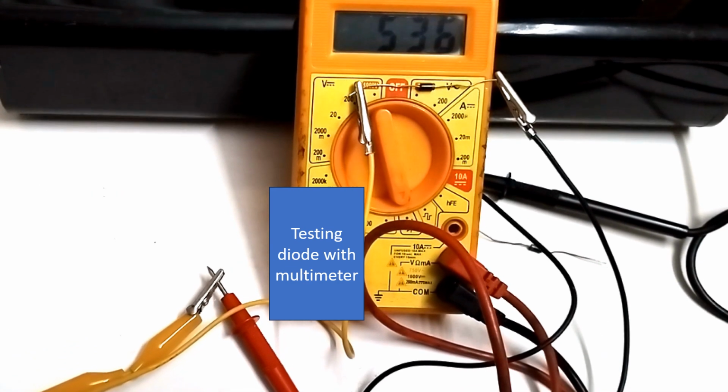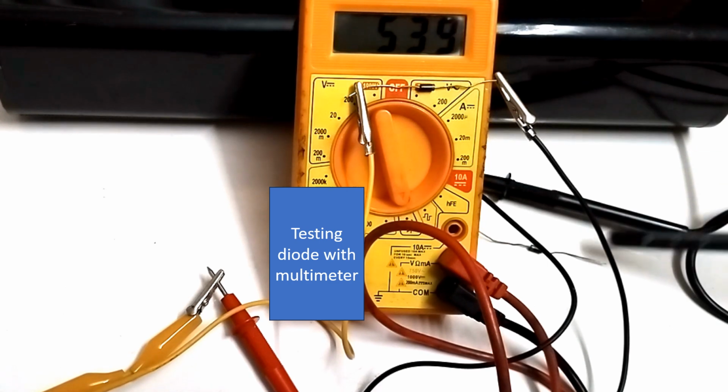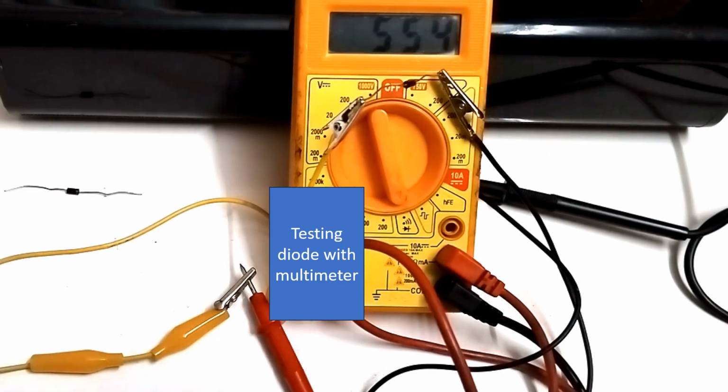Now I am testing another diode of the same type. You can see that there is a slight difference in the voltage across the diode in forward bias condition. It is 538 millivolts rather than 555. This was the diode which we tested initially, and this is another diode. There is a slight difference. Such variation can occur from device to device.